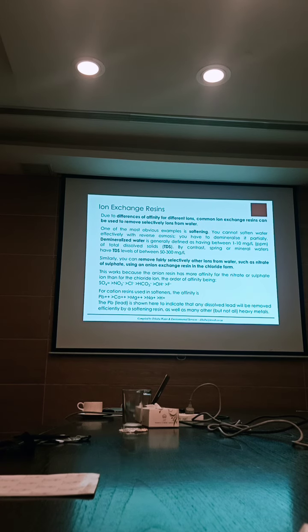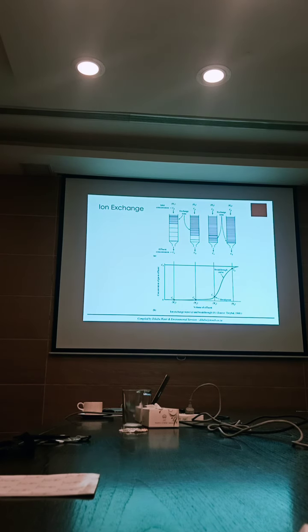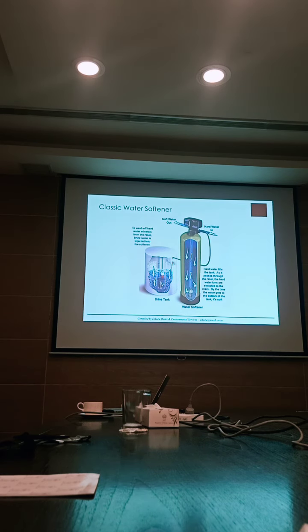So demineralization, what's demineralization? The removal of minerals from lots of salts, down to 1 to 10 TDS. So you can just pass the same water through a couple of ion exchange columns to demineralize it. You can distill it as well, I guess, but yeah, horses for courses. Were you going to ask something?